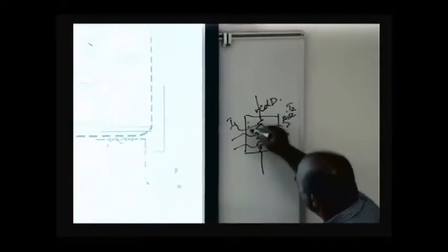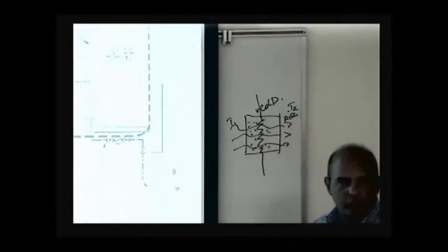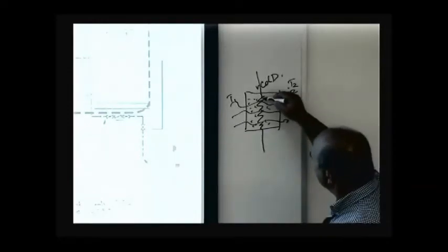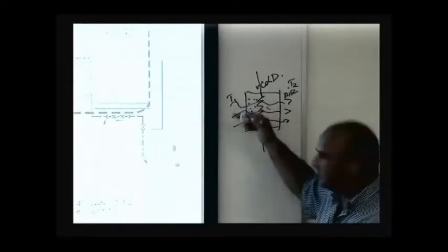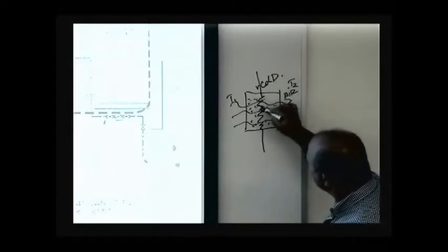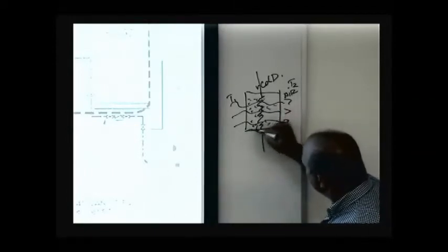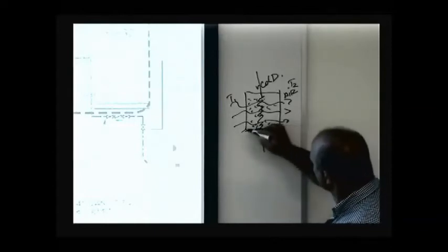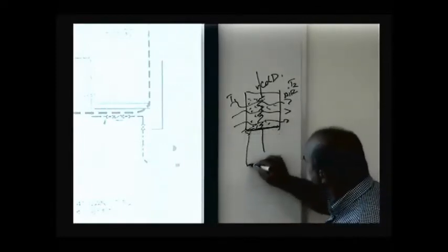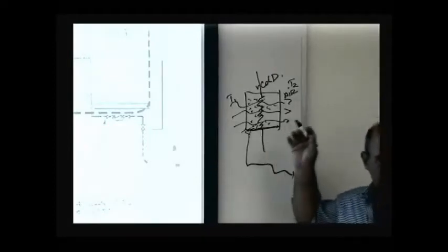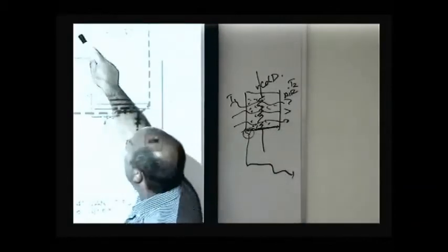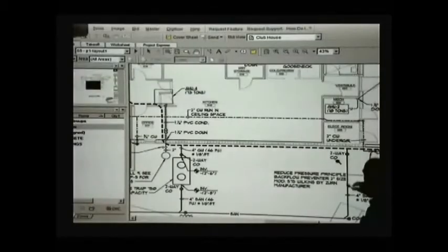So this air has moisture. It's a combination of water and air. So when it goes through the cooling coil, that cooling coil is at a temperature below the dew point of the air, so that some of that water that is going through is going to condensate on the cooling coil. So it's going to create water. Okay, it's going to accumulate water in a pan, and that water is drained to the sewer system. So you need to collect that drain, and that's why you're going to see that there is a line that goes to each one of these air handling units.